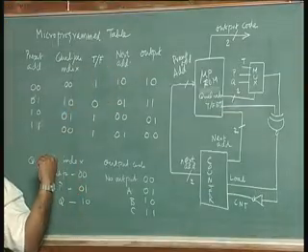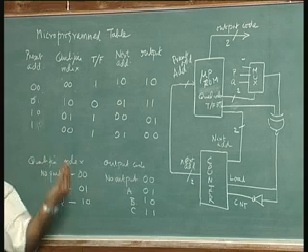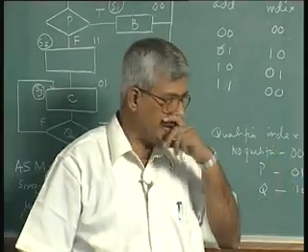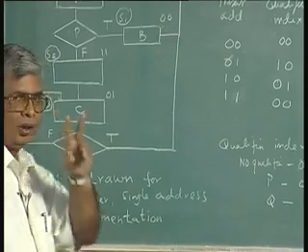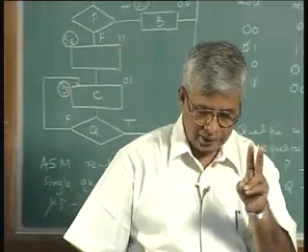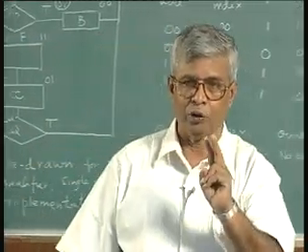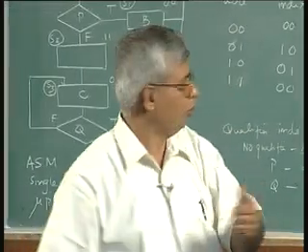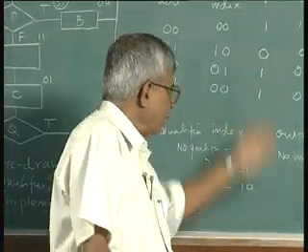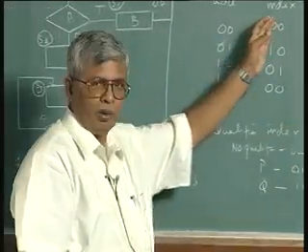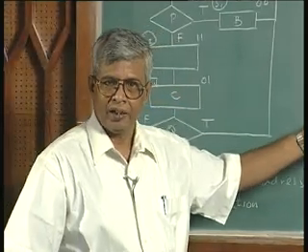It looks like a trivial example because I do not see any appreciable change in the size of the ROM. The reason is there are only 4 states, 2 address bits are required to represent 4 states, out of which 1 has to go for true false bit, and this particular example happens to be also 1 more bit has been added to the qualifier index.